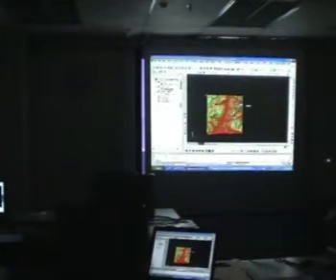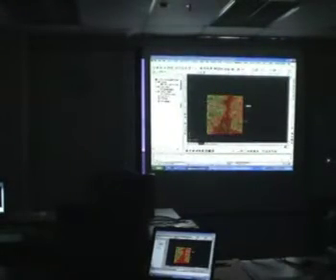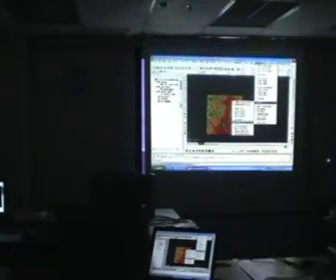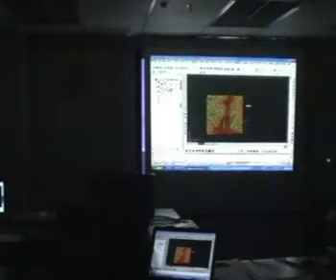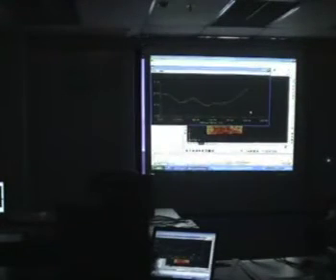Okay, just to cover a bit more about Land Desktop. This is another very unique feature that's been developed since Land Desktop 3. Let's say I just draw a polyline right through. I don't even have to draw it as a completely straight line. I'm just going to draw it as a line goes through, like this. And I'm going to use sections. Let's say I want to view a profile of the terrain. I'm just going to click this line. You can see the profile immediately.